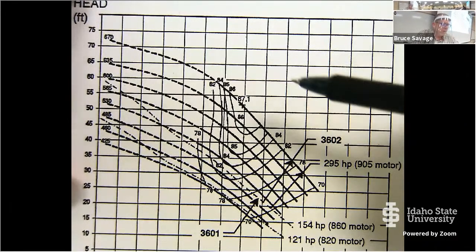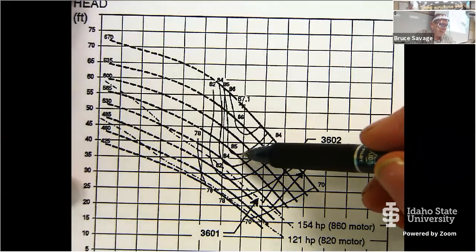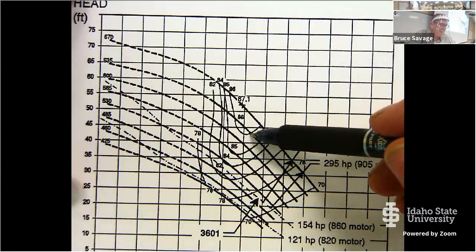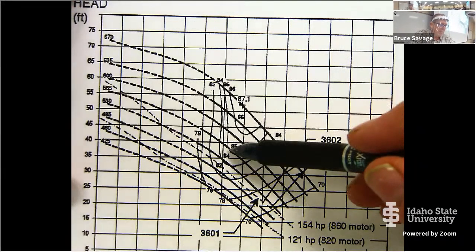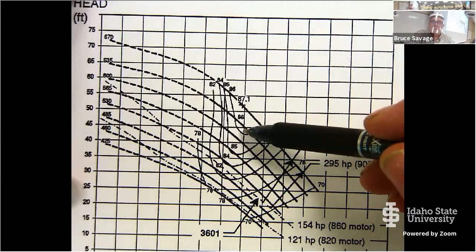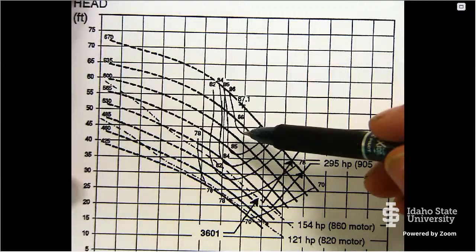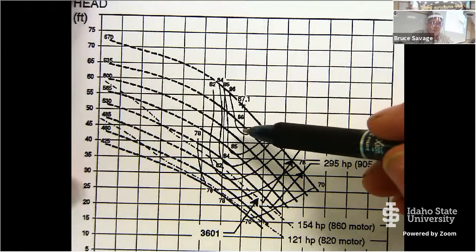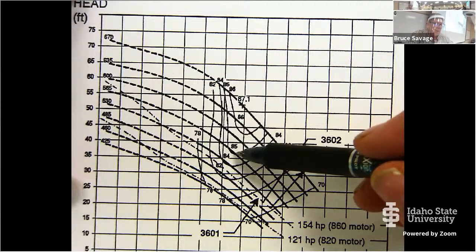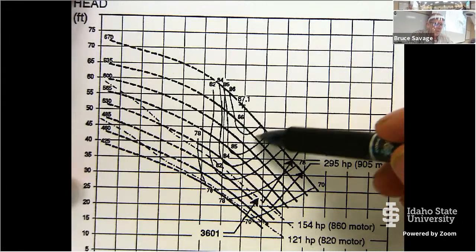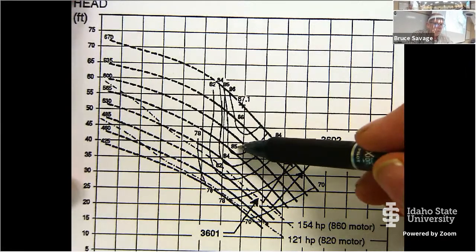So anywhere between 80, this one's 85 and this one's 86. Anywhere between those two lines, safe practice is to use the lowest, unless this gap is huge. If the efficiency is jumping by 5%, a 2%, I guess you could say I'm halfway there, so I'm going to pick the middle. But if they're 1%, just go with 85. So if you're anywhere in between these two curves here, you go with 85.